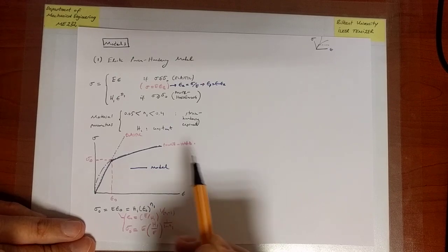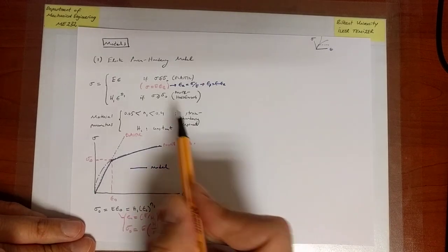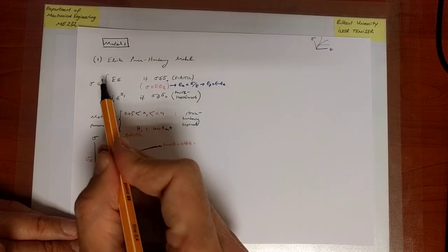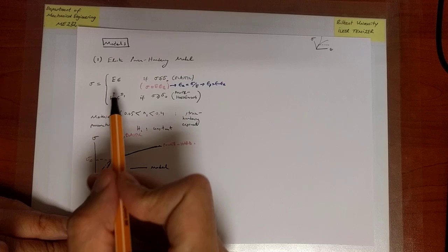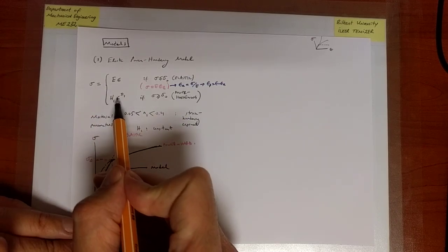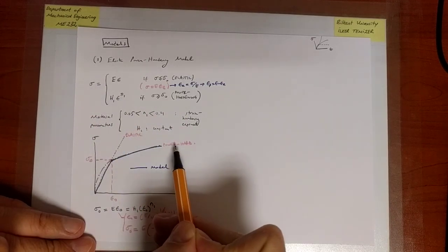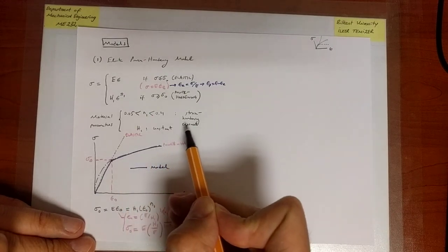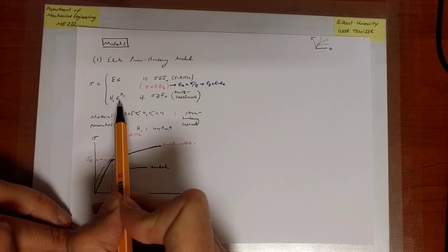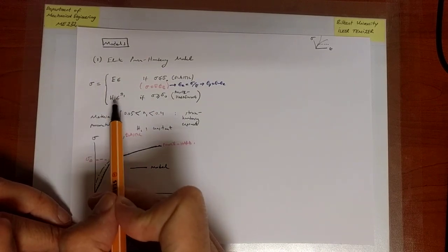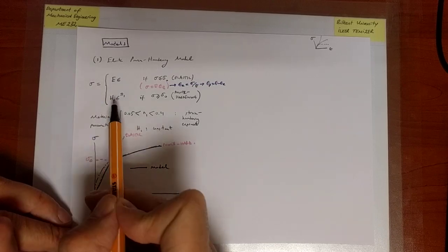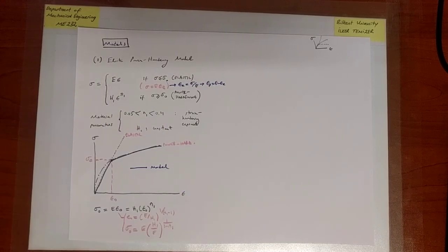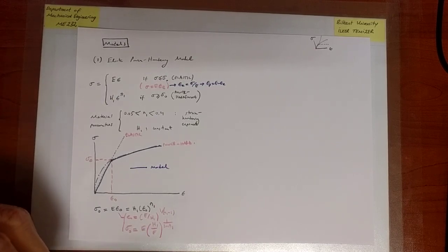It is the true stress strain curve that continuously increases. And this relation is predicting an ever-increasing trend for stress with respect to strain. So in terms of engineering stress strain it wouldn't work, because engineering stress strain starts to dip down after a certain while, whereas the true one will always keep increasing. So that relation towards the point of necking and beyond is certainly going to be used with true strain versus true stress, because only that one makes sense.